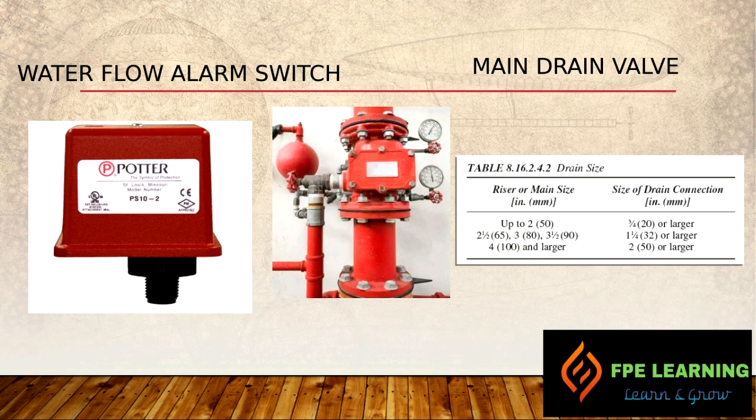On the right, we have a drain valve. As per 8.16.2.4.2 of NFPA 13, for an alarm check valve up to 2 inch, we need at least a 20 mm drain valve. If it is 2.5 inch to 3.5 inch, it is around 32 mm, and for 4 inch and larger, we need a 2 inch drain valve. Normally we need a drain valve to discharge water in case of maintenance, or once the system activates, we have to remove water from the system. We need a drain valve to drain the complete system.